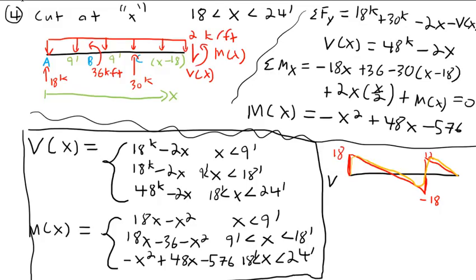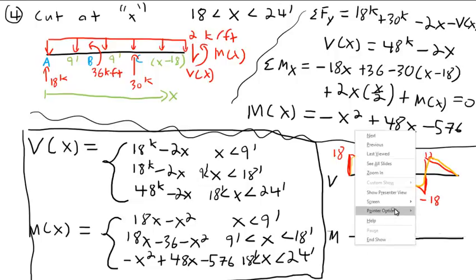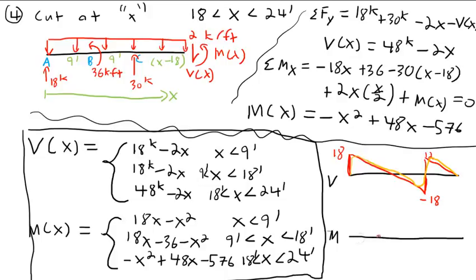So, relationship between load, shear, and moment. Actually, let me go ahead and draw the moment diagram while I'm at it. Show you what this would look like for this one. There's the M. Sorry about that, I missed a bit of my own notes. It's going to come up like here in parabolic behavior. It will have a peak of 81.